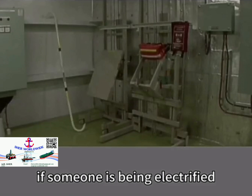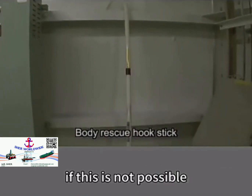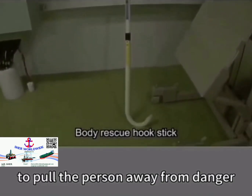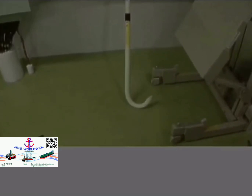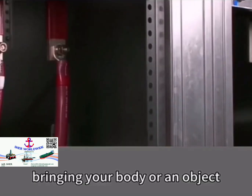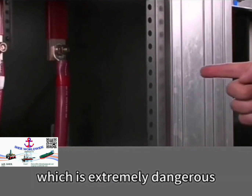If someone is being electrified, your first step is to shut off the power source. If this is not possible, then use a body rescue hook stick to pull the person away from danger. Bringing your body or an object near a hotline can cause an arc discharge, which is extremely dangerous.